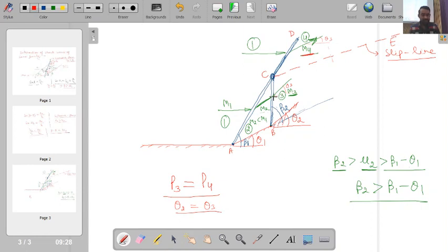So obviously it is not possible to maintain the same set of properties over here in region 4 and region 3. This necessary condition for a straight slip line to occur is impossible to achieve in this situation, because here the flow is passing through a single wave, and here the flow is passing through a set of two waves. So ultimately I cannot ensure that both the properties, pressure as well as theta, are being maintained at the same point of time.